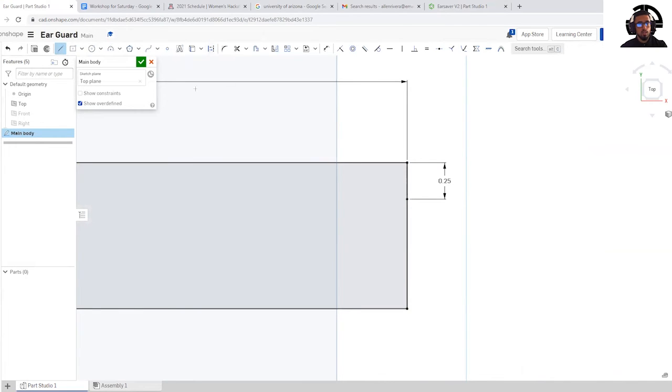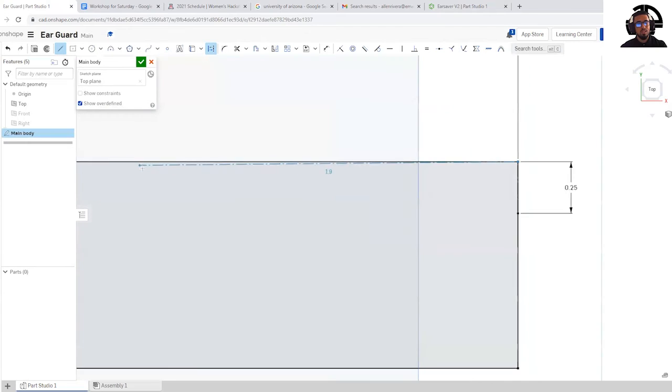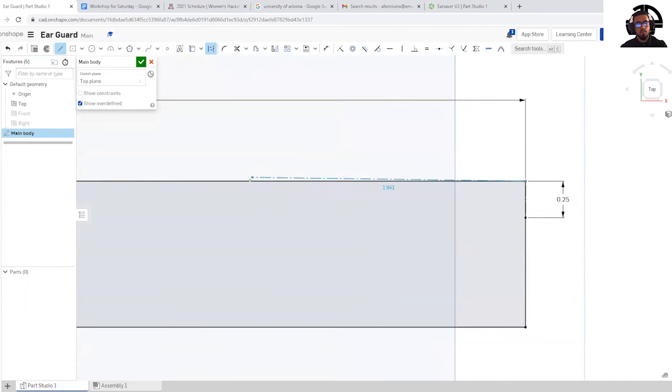So now what I would like to do is create another construction line. And now you see when I click on construction line and line, both are highlighted. But when I unclick it, it takes the construction line away. So basically, I want another construction line going widthwise, so that way I can know where I want my spline to go. And I want it to go, let's say, so I have it 7 inches, maybe 2 inches on both sides. So that way I have a good amount of room for text.